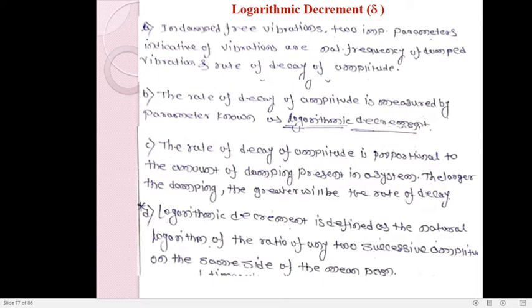But in the case of an underdamped system, the system will perform further oscillations depending upon the damping conditions. The value of zeta should be less than 1, but if the value is 0.1, you can easily say that the system will perform more cycles as compared to a system where zeta is equal to 0.9.